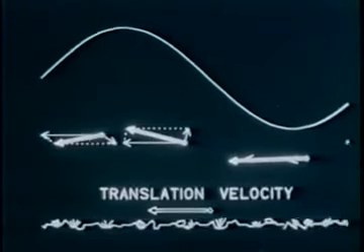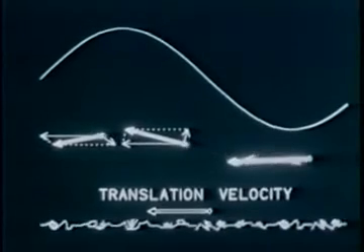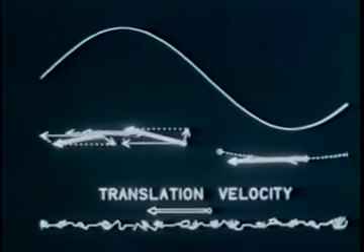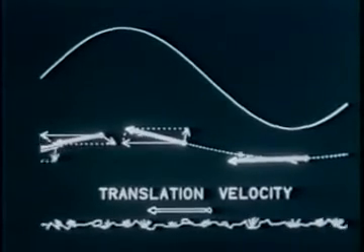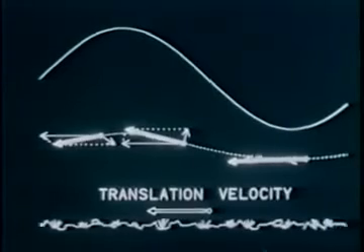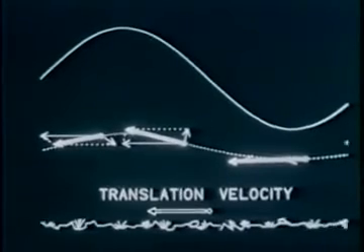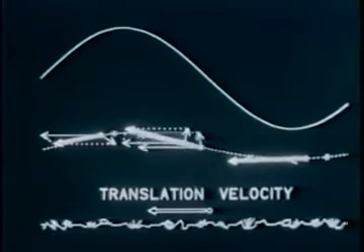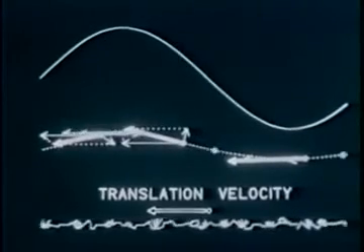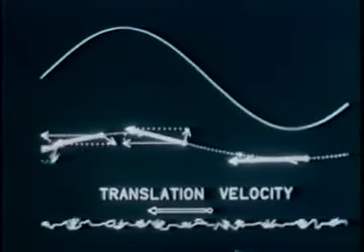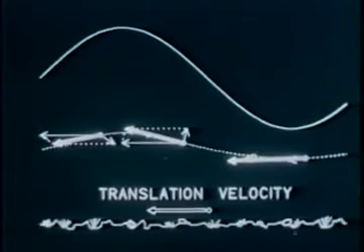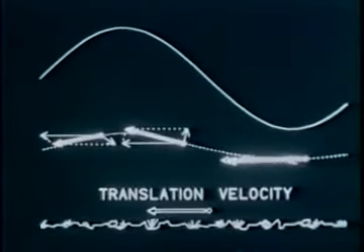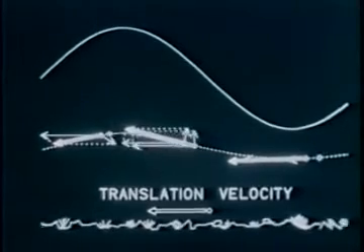The path lines, which are also streamlines in this frame of reference since the flow is steady, resemble the form of the free surface. As a material point passes through each laboratory point, its velocity is instantaneously the same as that of the laboratory point. It is partly this possibility of eliminating one of the variables in the analysis, time, that makes the Eulerian representation more attractive.